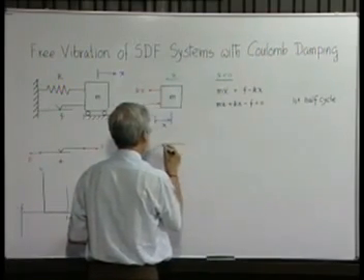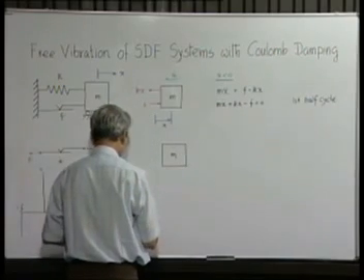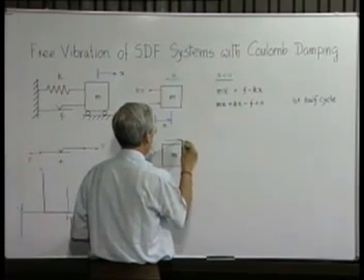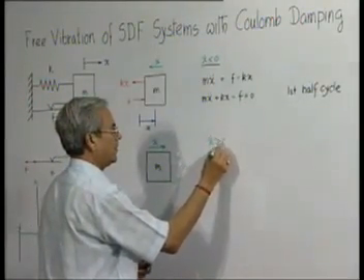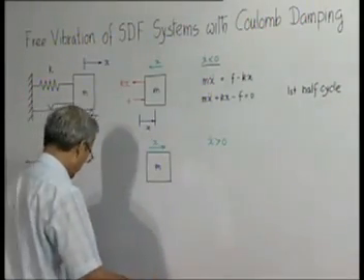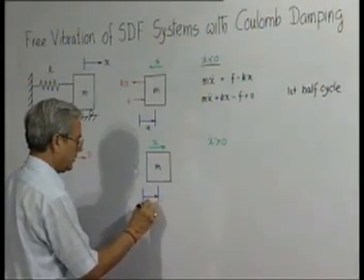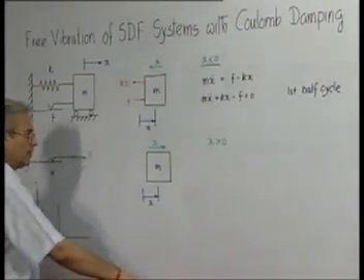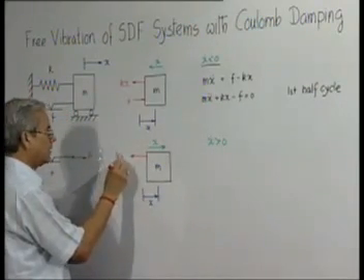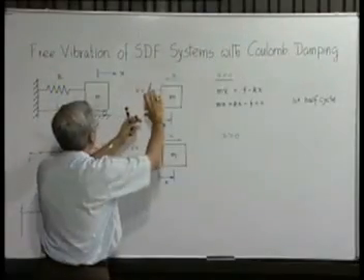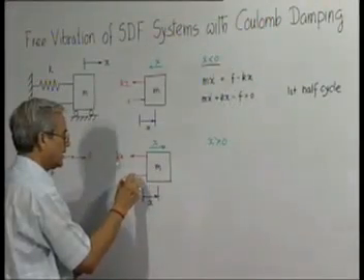Now in the next half cycle, when the mass moves from left to right, x dot is positive, then again at a similar location, at a position x from the equilibrium position, the spring force will again be kx, and since it is now moving in this direction, the friction force on it will be in the opposite direction. Friction is always opposite to the relative velocity.